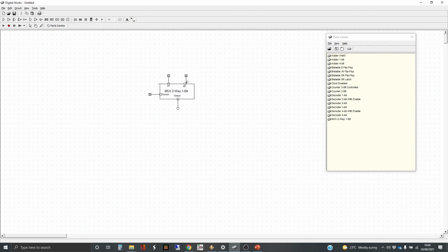So, just to reiterate how this should be working, we've got 2 inputs, and control should choose which of those inputs is going to the output. Let's run it in simulator. At the moment, control says that we're using the 0 input, and so I put that high. Then there's a slight delay in the simulation, but then the output goes up. And if we make changes to A1, it's not doing the output. And if our control goes high, it should then pay no attention to A0, but A1 is routed to the output. There we go. That's the very simplest kind of multiplexer that you can have.